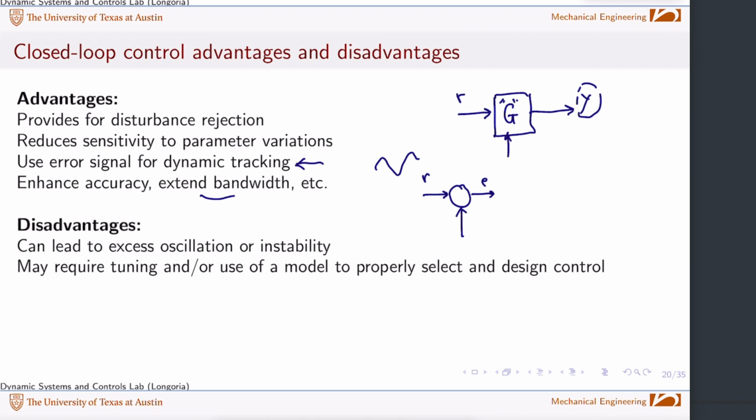And so, in fact, that points to one of the disadvantages. Whereas if you have an open loop control system and you know that you've studied it, it's not unstable, and you're just putting inputs and it's tracking it, the worst that can happen is you're off. But generally, you can't make that system go unstable, right? By closing the loop, because you can change the system, basically the characteristic equation, right? You can change the poles of the system. You can make it unstable based on what you do to it with the controller.